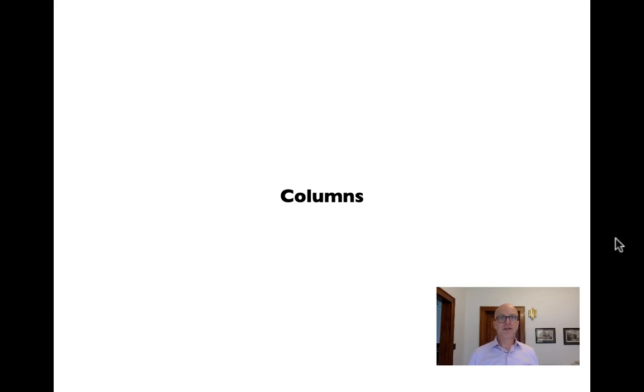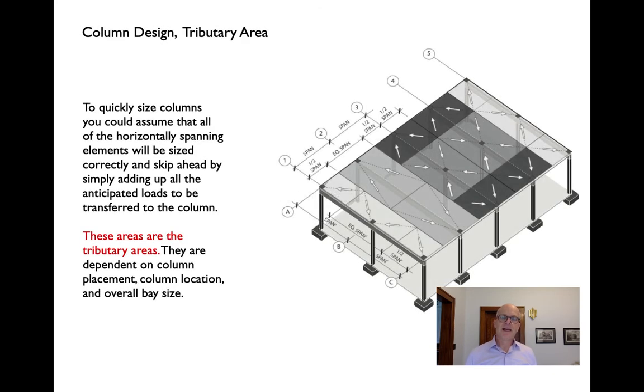Okay, those beams all sit on columns, and for column design, remember that we're basing the design on the tributary area. So we're dividing up floor plates based on column locations. We're assigning every column a fair amount of the floor. If we have a rectilinear grid, we're drawing lines at the midpoint between any two columns and then assigning each column a tributary area based on that.